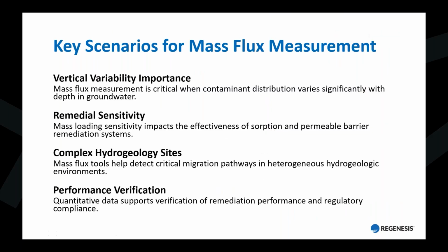So just in closing, there are a lot of scenarios where this mass flux measurement can be really important. One is just in your initial site investigation, having a good understanding of contaminant distribution and the vertical delineation can be really helpful in understanding the dynamics of that plume and really refining your conceptual site model.